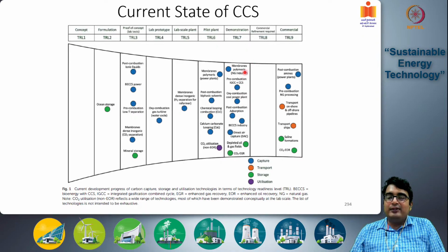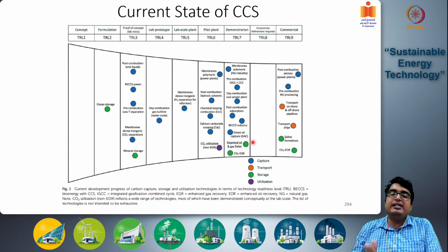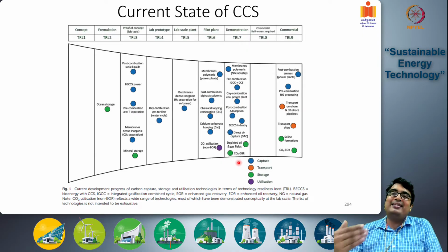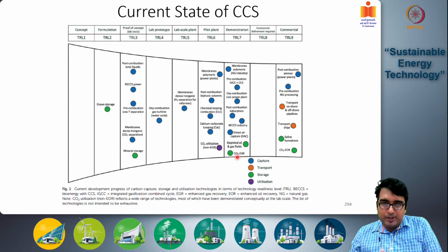Demonstration stage: you have the semi-permeable membrane based technologies for capture, post-combustion adsorption technologies, bioenergy based CCS technologies, direct air capture of CO2. These are all demonstration levels. These are depleted oil and gas fields. So we are currently demonstrating the CCS technologies in depleted oil and gas fields. Then CO2 based enhanced gas recovery from coal beds, etc. This is also in the demonstration stage.